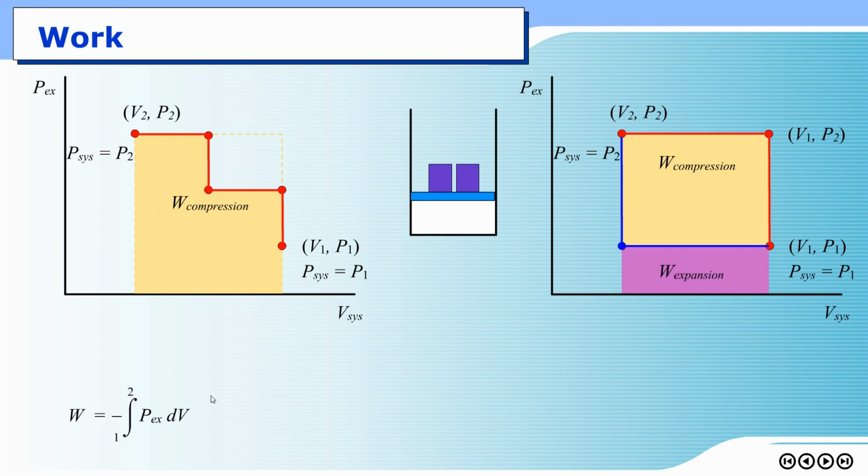If you integrate this red line, basically you find the area underneath it, you get the compression work. And you can see that the compression work in this case is smaller compared to what we got earlier from putting one mass of 100 kilograms, only one mass at a time. One mass of 100 kilograms right away.